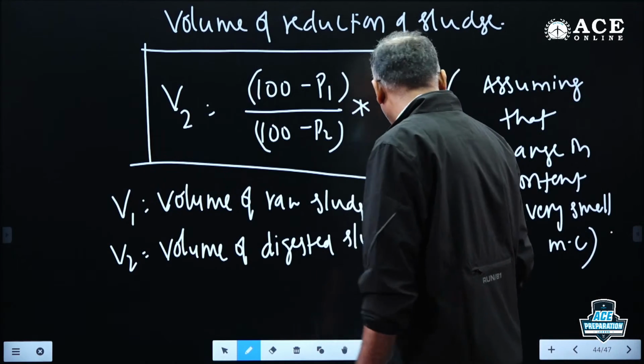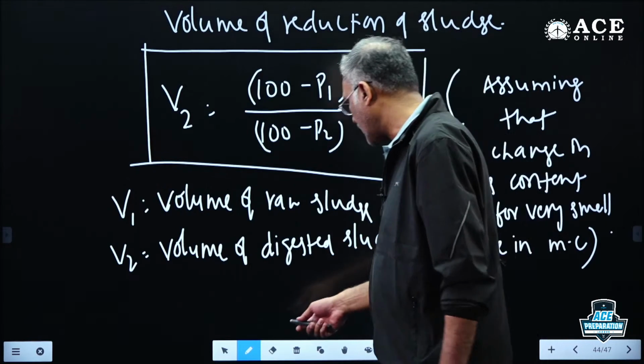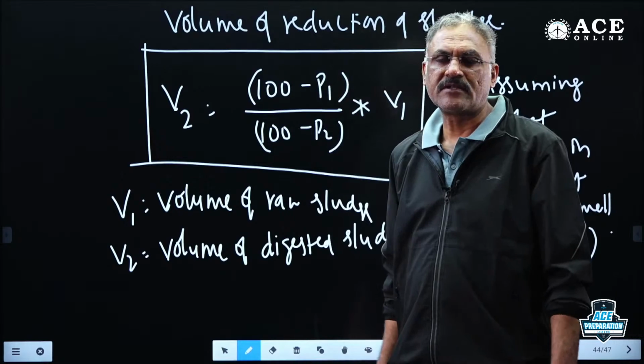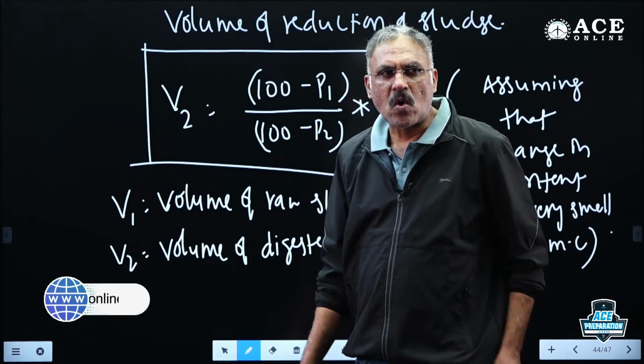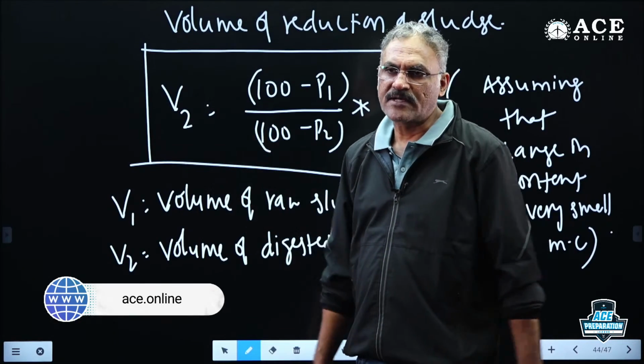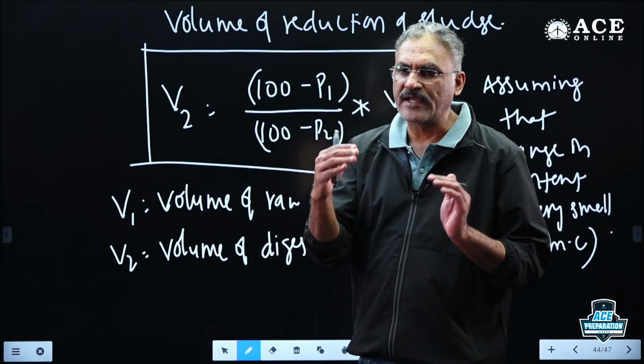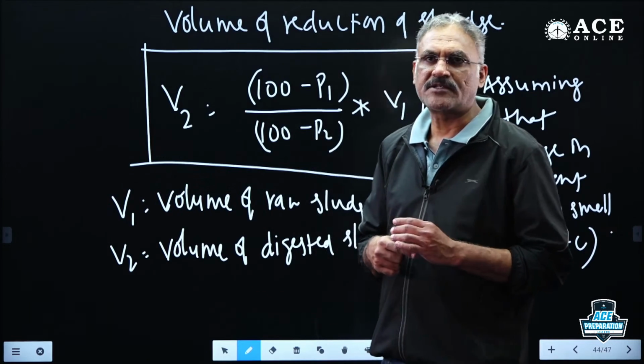Similarly, in the sludge digestion process, theory questions are also being asked nowadays. What is the temperature at which this digestion we need to carry out? Sludge digestion occurs slowly and depends on temperature. As temperature increases, the time to carry out digestion decreases. So it is temperature dependent. We discussed already, a mesophilic range of digestion is there and a thermophilic range of digestion is also there.